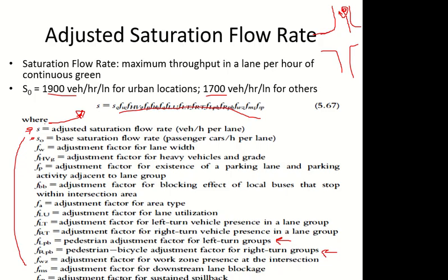And then we have sustained spillback. This is the two intersection case. So you have one intersection. Spillback is when the queue from this intersection is going up to the previous intersection. This is called spillback, when the queue from one intersection blocks the upstream intersection as well. This is called the spillback case.